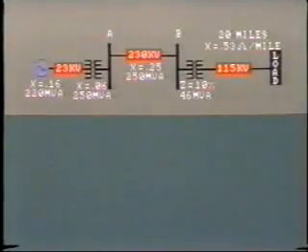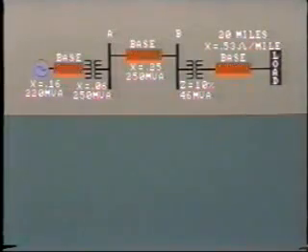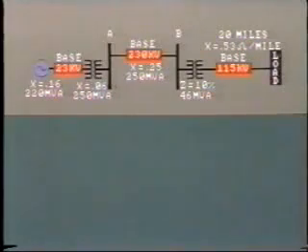So now that we've established the utility of the per unit system, let's look a little closer. Usually, base voltage and base voltamperes are chosen arbitrarily, and then base impedance and base current are derived from these. Base voltage should be chosen to be the nominal voltage in particular parts of a system. In our example, that would be 23 kV, 230 kV, and 115 kV, base voltage for these specific areas.